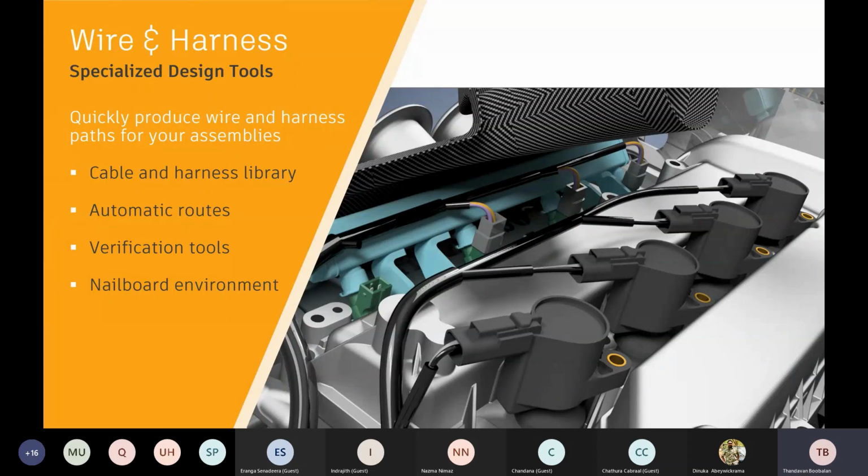I told you, right, there is an AutoCAD interoperability, so you can link that into Inventor. You would have already assigned some pin assignments in the electrical circuit, right? So based on that, it takes all the data, and in Inventor you can see the 3D routing. Okay, so it provides a proper 3D routing. That's the kind of interoperability and seamless integration between AutoCAD Electrical as well as Inventor.